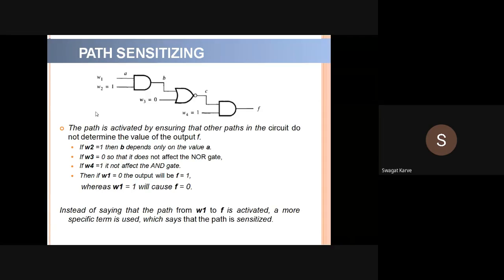Now you can assume that, instead of checking all 14 conditions, we have reduced the headache to only 4 conditions. The test vectors will be 16, because you have 4 different inputs, so 2 raised to 4, that is 16, from 0, 0, 0, 0 to 1, 1, 1, 1.